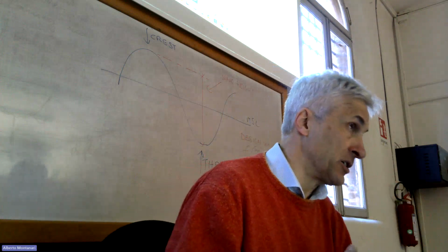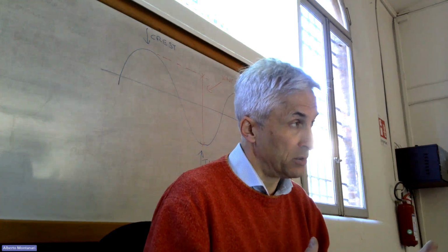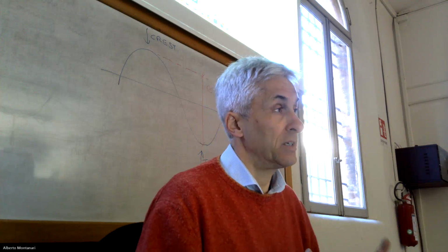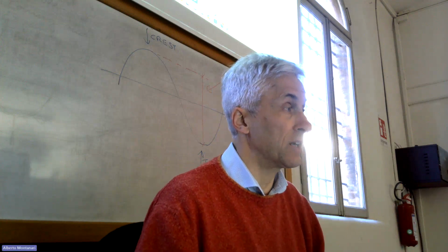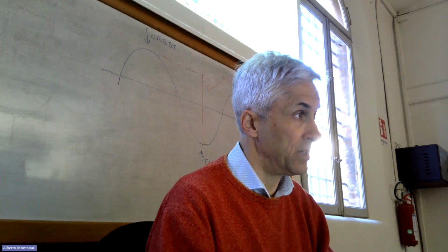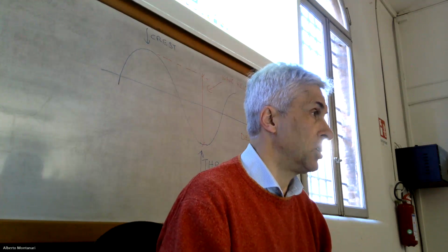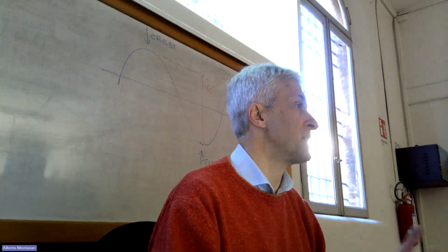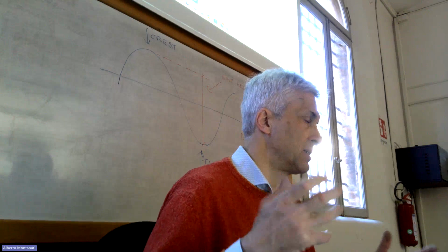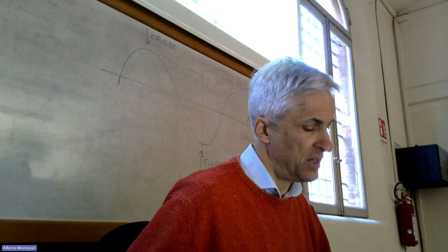But you have to be aware of uncertainty. So you have to know that if your observation period is shorter than the return period, you are very likely to get a lot of uncertainty, and therefore you have to introduce a proper safety factor. If the guidelines tell you to adopt a safety factor, for instance, we discussed the GAST factor, which can be intended also as a safety factor, a correction for uncertainty.